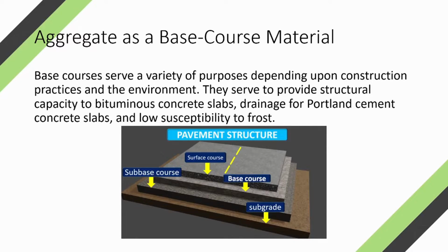So base courses serve a variety of purposes depending upon the construction practices and the environment. They serve to provide structural capacity to bituminous concrete slabs and drainage for the Portland cement concrete slabs, and it lowers the susceptibility to frost.